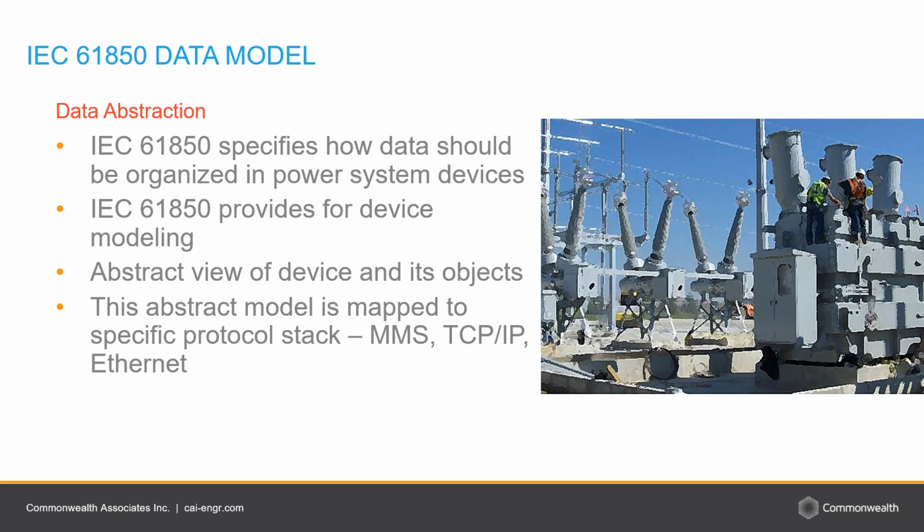So let us talk more about data abstraction and data modeling in the 61850 standard and how it comes about. This standard is unique in that it provides a comprehensive model for how power system devices should organize data in a manner that is consistent with all types and brands of devices.